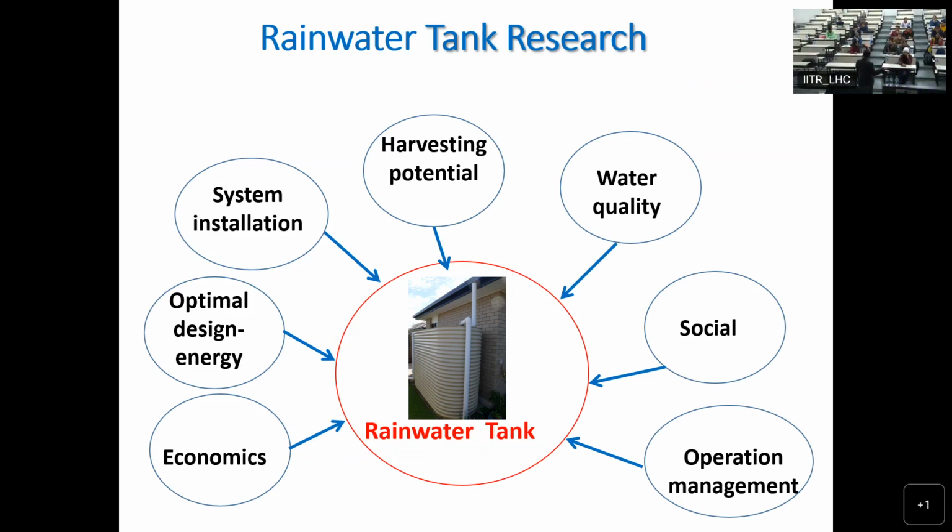When we are calculating the volume, we are focusing more on the dry spell, meaning how long the dry period is. That's why I'm moving away from that. What I'm saying is, don't use the dry period for calculating the volume. Let's adopt another way of doing it. Every day, you see how much is the rainfall and how much is the demand. When there is rainfall, see what factors apply to collect how much water is coming in, based on the factors you have considered. So you're not looking at the dry days.